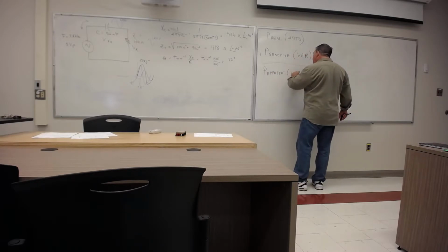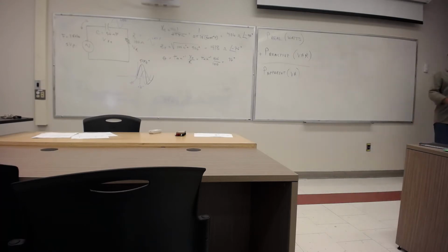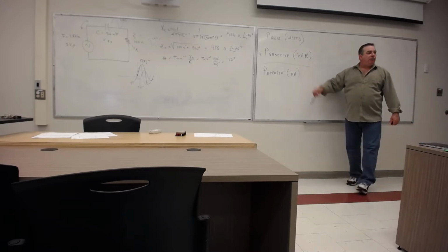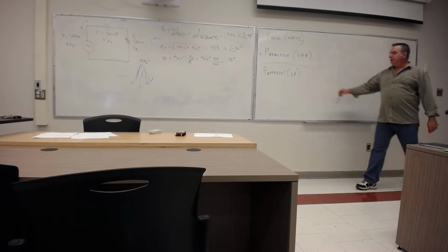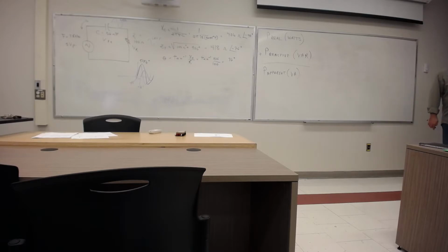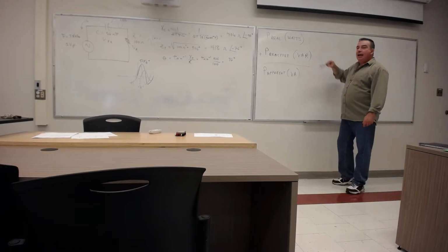And that's in VAs, volt amps. Whenever you get a transformer, if you're speccing out a transformer for an application, it's always rated in volt amps, because they really expect stuff to be out of phase. Okay? So for instance, if you've got an application and you figure you're going to need 30 watts, the transformer might be rated for 30 VAs. You're going to need at least that, if not a little bit bigger. Just to give you an example, transformers are always in VAs. And VAs is the sum of real power and reactive power.